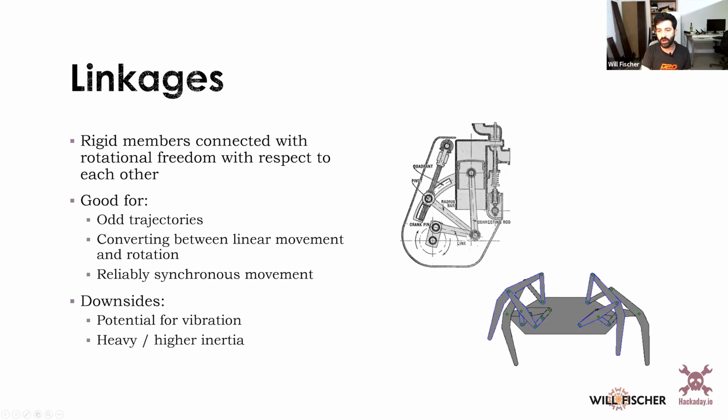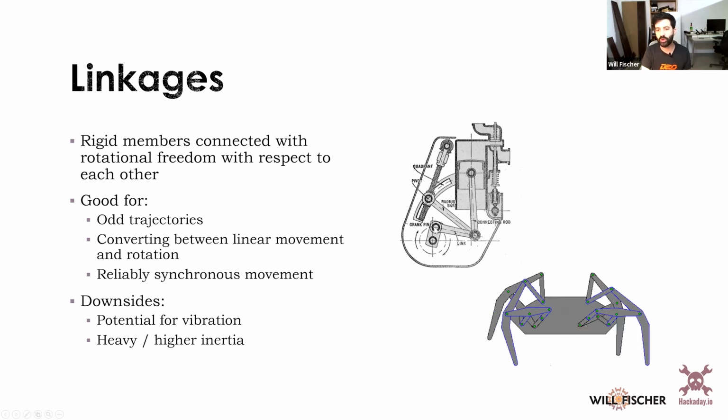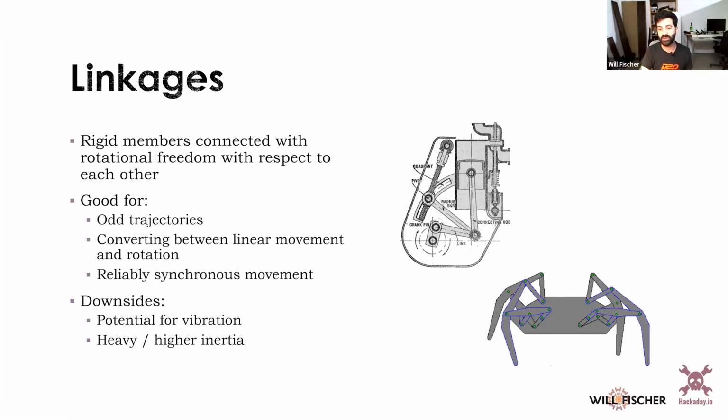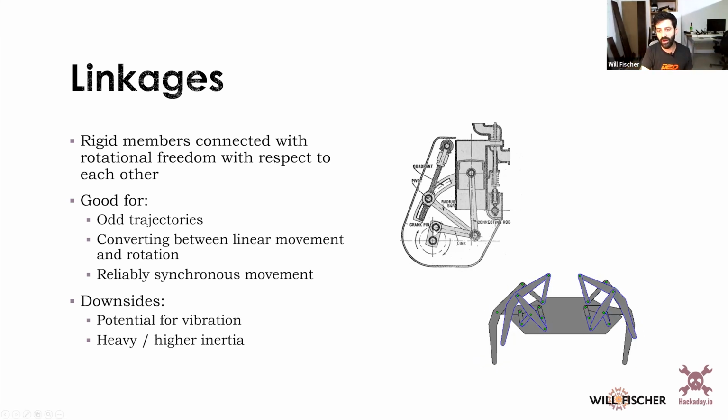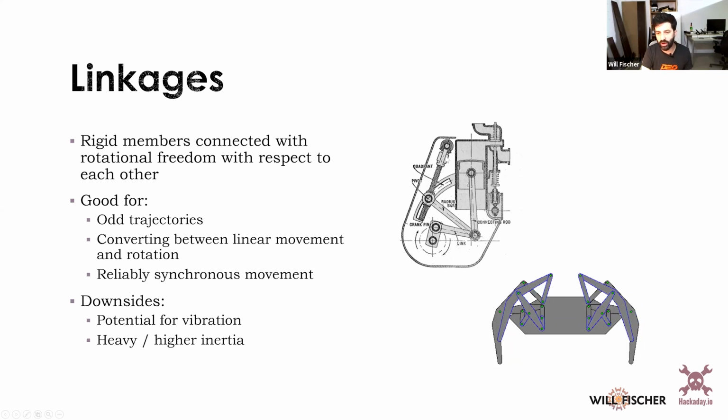So you see that there are connecting rods and things. These are linkages, so you have rotational degrees of freedom between them, but then they don't translate, so you can fix them in places. So this is a 1 degree of freedom system in that you've constrained it such that the rotation of this element becomes the translation of this element, assuming that you're not threading in and out adjusting this thing.